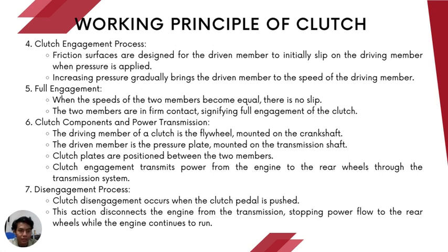Fourth, clutch engagement process. Friction surfaces are designed for the driven member to initially slip on the driving member when pressure is applied. Increasing pressure gradually brings the driven member to the speed of the driving member. So when the speed of the two members becomes equal, there is no slip. The two members are in firm contact, signifying full engagement of the clutch.